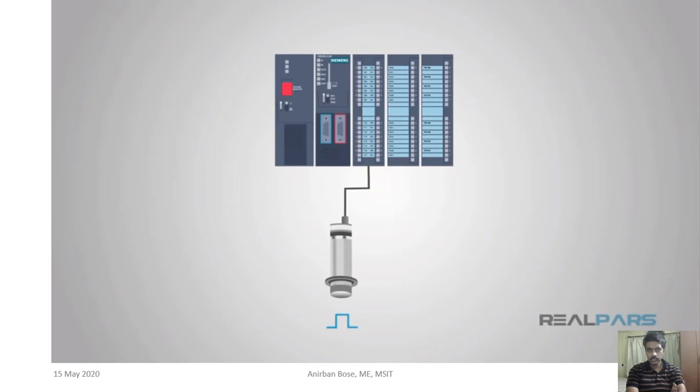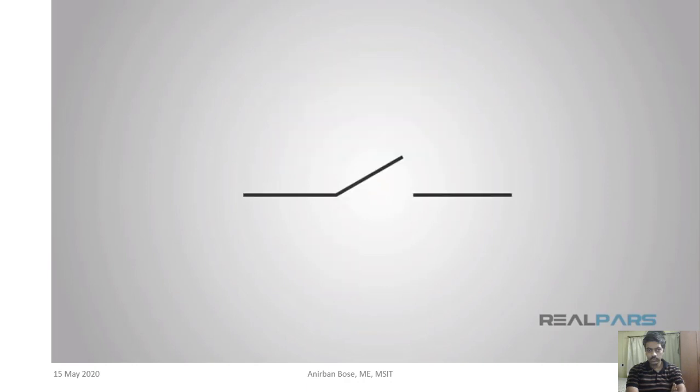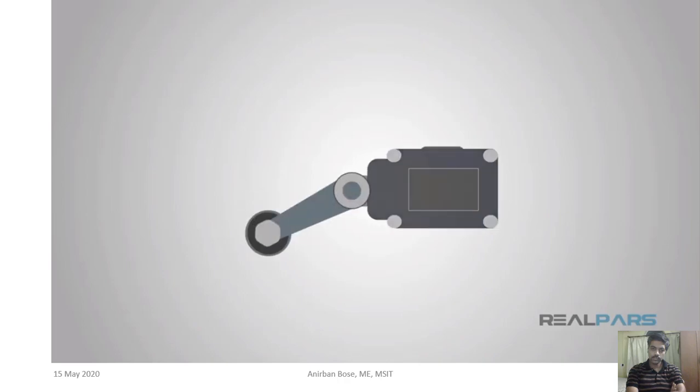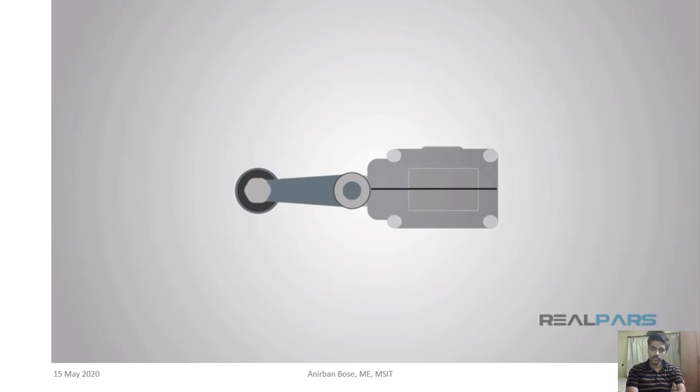In theoretical terms, we're referring to something that returns one or more bits of information per sensor. Initially, they were simple: a contact that touched another contact when something got where it was supposed to stop. In those old machines, this often meant 110 volts exposed for the operator to touch, or passing through the machine frame. Unsafe under any condition, and probably illegal in today's safety-conscious world. Later, these became a switch that flipped when something got to a position. These are referred to as limit switches, and are still in use.